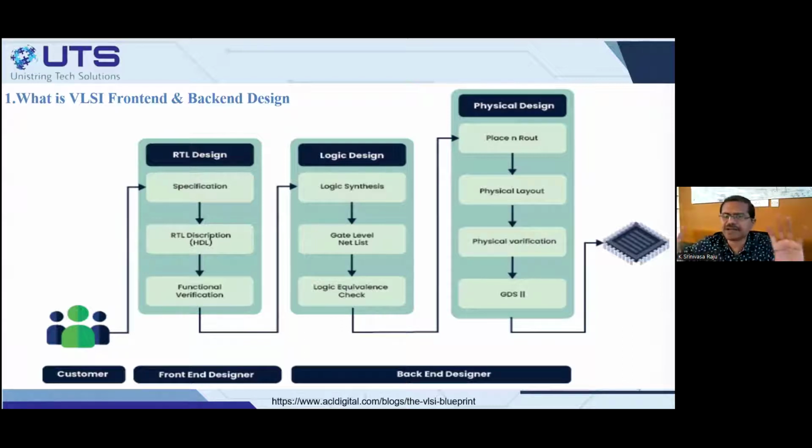It's very simple. Maybe when we start discussing the VHDL syntax and Verilog syntax, we will go deeper into this aspect. RTL is nothing but a specific digital design style, mainly suitable for coding techniques like VHDL and Verilog. You describe your digital design requirement as data moving across registers. First register, second register, third register. Between first and second, you have a mux. Between second and third, you have some comparator. That's the concept of RTL.